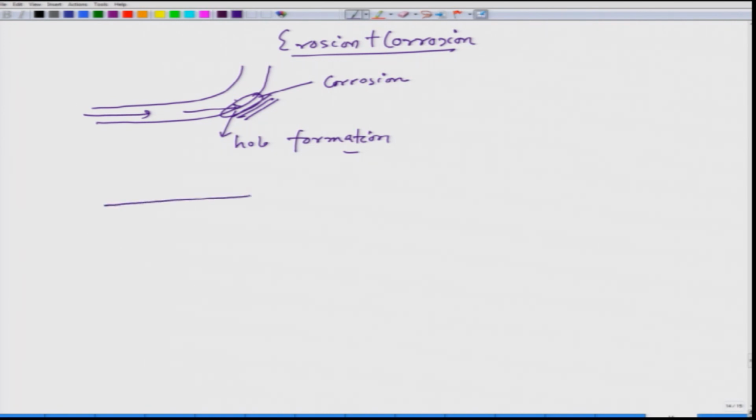If we have a pipeline design like this, the erosion corrosion tendency would be much higher, it will be felt more because of the effect of turbulence. If we have a flat section, a gradual change in slope, or a corner, then the erosion effect would be less because the turbulence is avoided. These are typical design aspects.